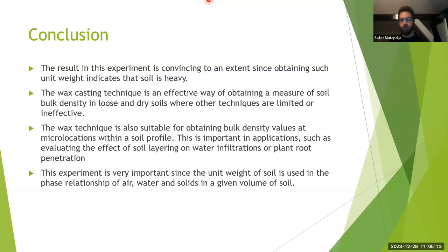It usually works best for clay, but if you're going to do proper compaction, you're going to have some sand there, some gravel there, because it's easier. You need a bit less water, and then you do your Proctor test, optimum water content, put the water inside, compact it, and that's it.